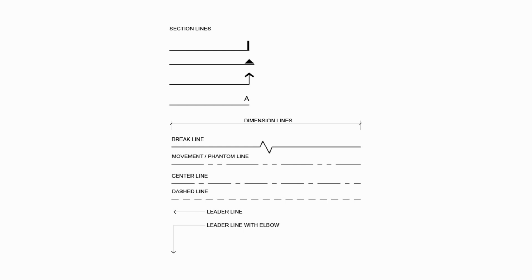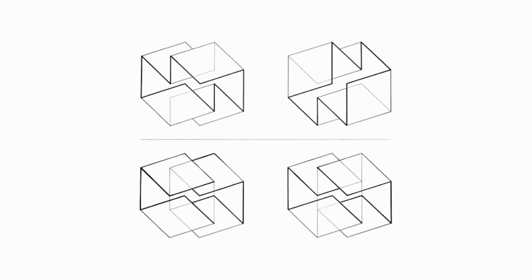You guys get the idea. Most of this is annotation-based line weights. So here's the same shape, the same set of lines over and over again. And if you squint at this, the shapes look totally different because of what is darker. That's what stands out. That's what comes forward. And so even though this is the same grouping of lines each time, we see different objects out of it. Do you guys see how that happens? And so that's all done just by your line weights.